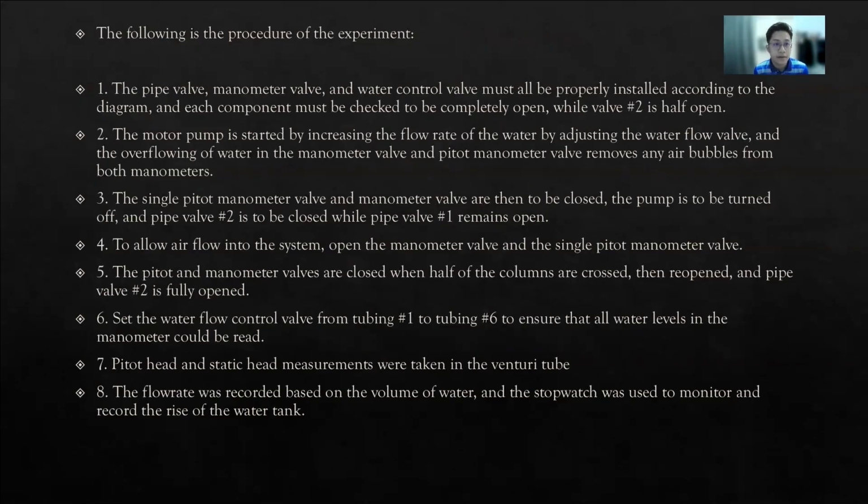So the following is the procedure of the experiment. Number 1, the first step is the pipe valve, manometer valve, and water control valve must all be properly installed according to the diagram, and each component must be checked to be completely open, while valve H2 is half open.